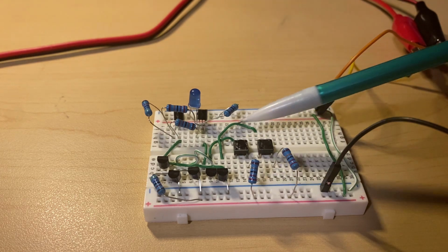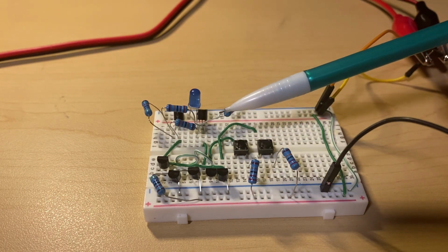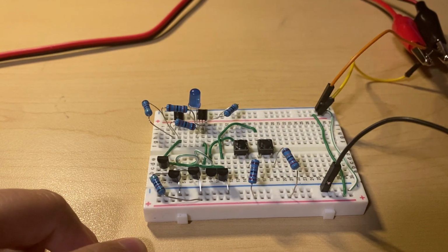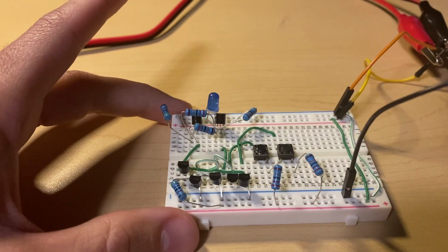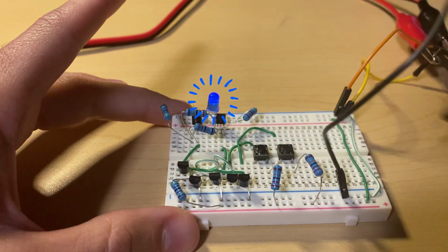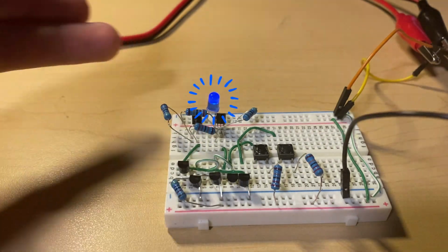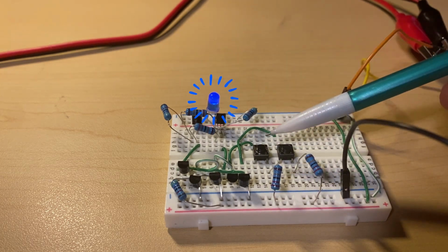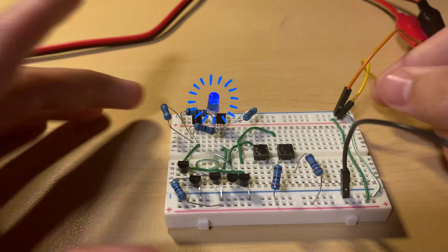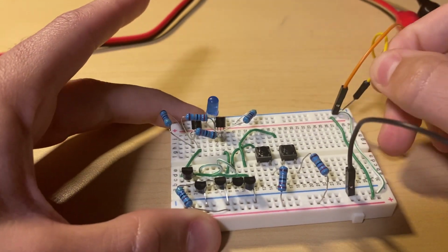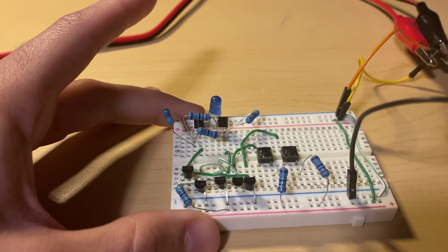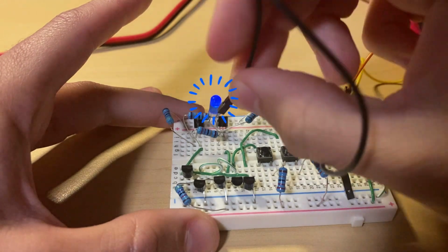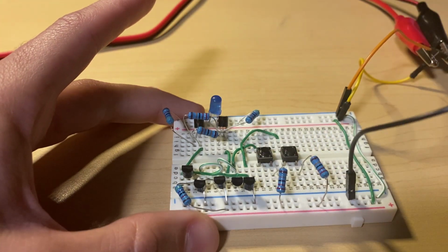And this is technically a data latch, but to go even simpler, this area right here is an SR latch. The way it works is there's a set and reset. So we plug the pin in here, we set it on, and now the electronics remembered that we wanted the state on, and it's going to be on forever until we either unplug the power source like this, or we go into the reset pin. So let me set it like that, and then this is the reset pin right here. So now it's off.